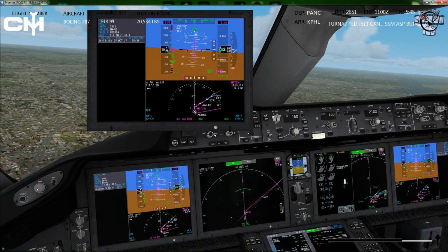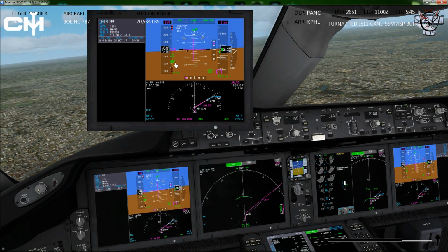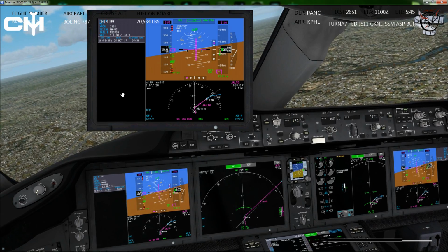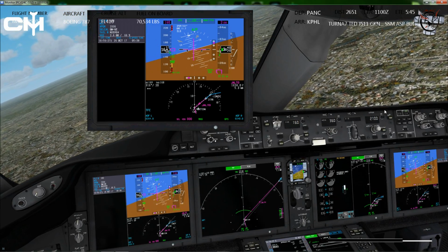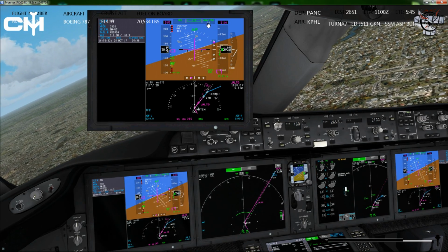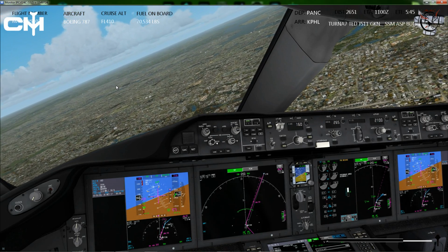I mean, 160 knots is pretty slow, right? And you can see we're just above our maneuvering speed for the flap setting. So it should lock. There it is. Now it locked on. You see it flip green right there. Now we'll hit the approach switch. It'll stay locked onto the localizer, and now the glide slope turns white like that. So let's go ahead and drop our landing gear now.